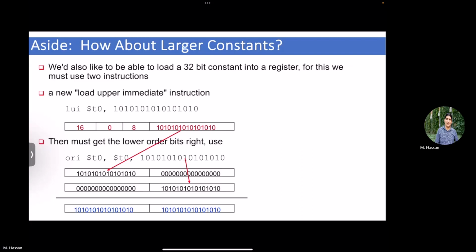Make sense? Why might this be related to the discussion we're having right now? Because I can add bigger constants or multiply them or do any operation with them by understanding that I can manipulate the 2 halves of the register separately. We said our immediate value is 16 bit, correct? Which in fact matches the width of half of the register, right?